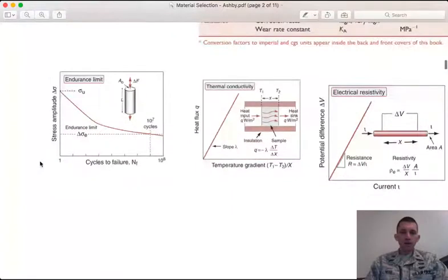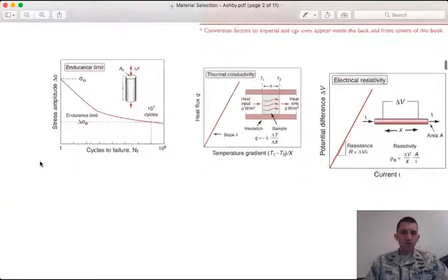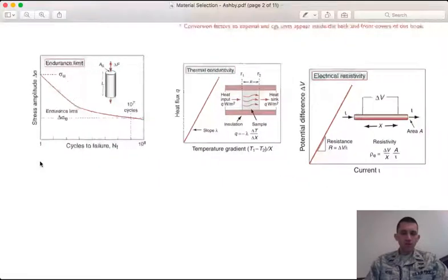And here at the bottom, we just have a couple of charts that display that kind of as a review for some of those other material properties. Remember here, this would be fatigue testing. We have the stress amplitude as you cycle that stress, and your cycles to failure, right? So this would be probably a material like aluminum, where you don't see a hard fatigue limit, right? As you go up in cycles, it continues to go down, even though the rate of decrease will slow down.